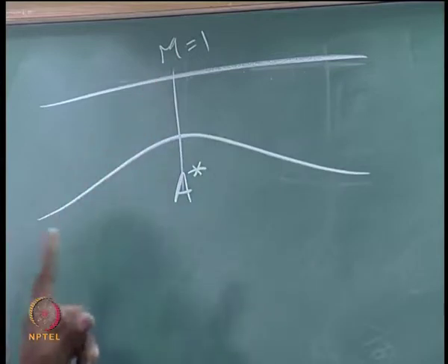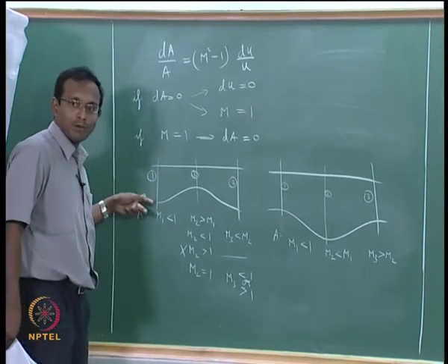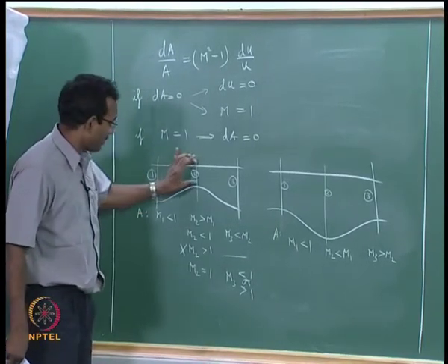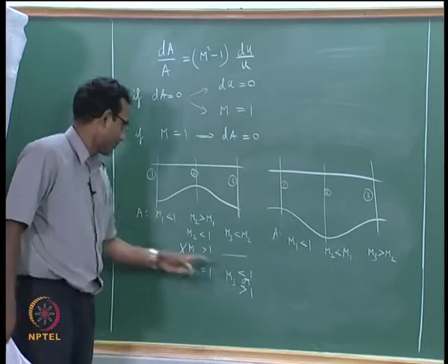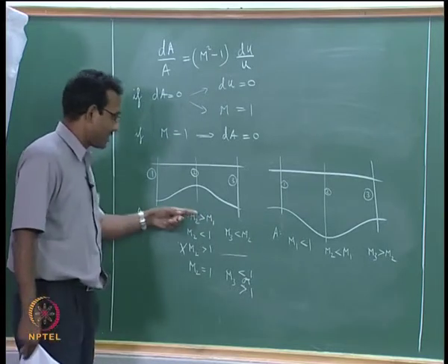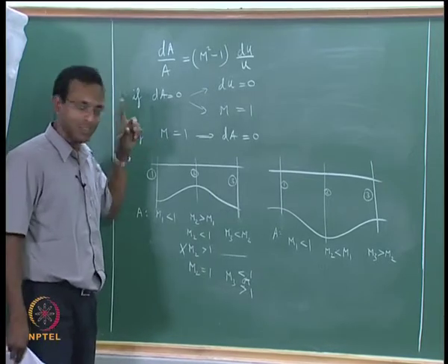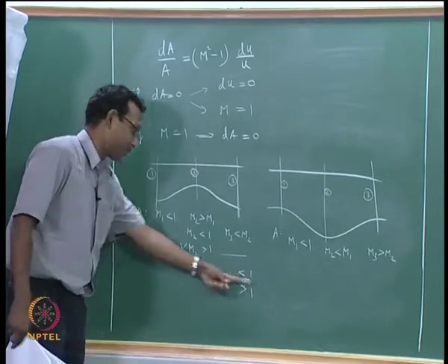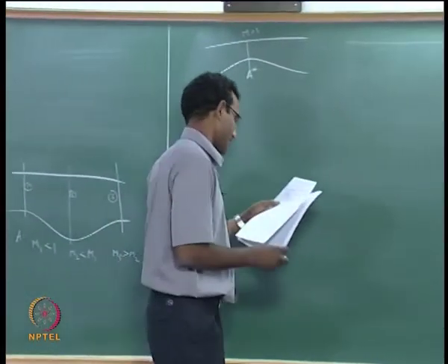There is also a possibility, like I will go back here, that from here I start with say Mach 0.2, it went to a higher Mach number, but it did not reach. It need not always take this path, it can also take this path. Let us say it did not take this path currently. We are considering a duct which has this particular path going through. That is the path you are going to consider.